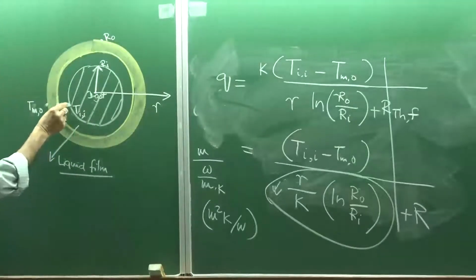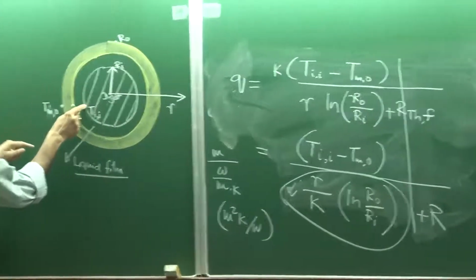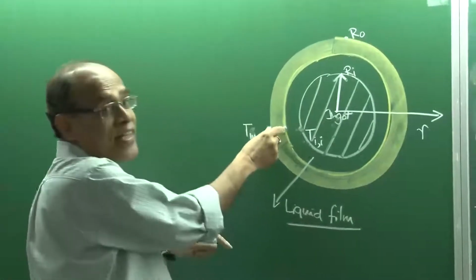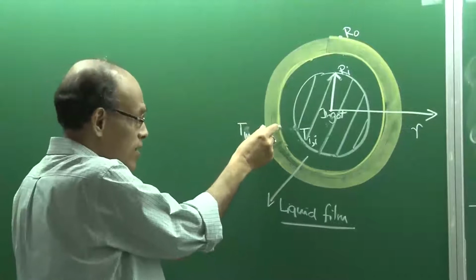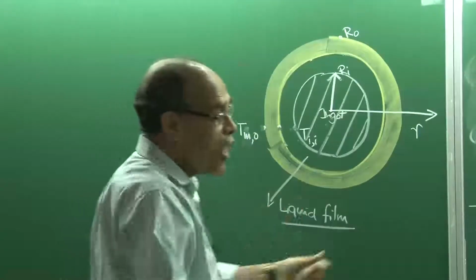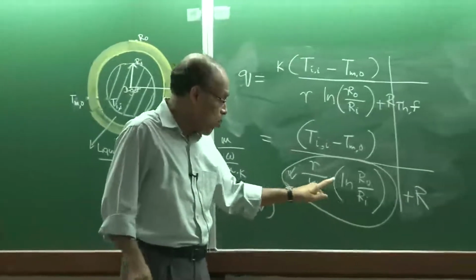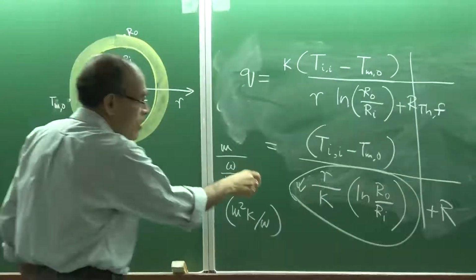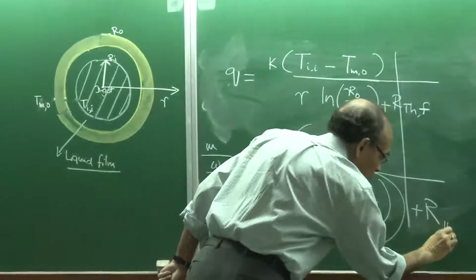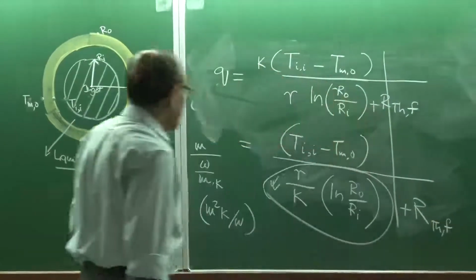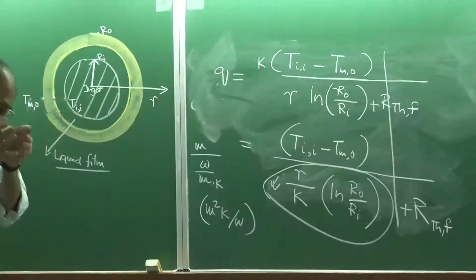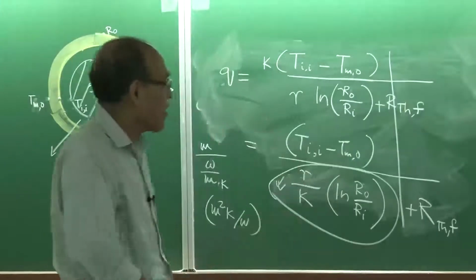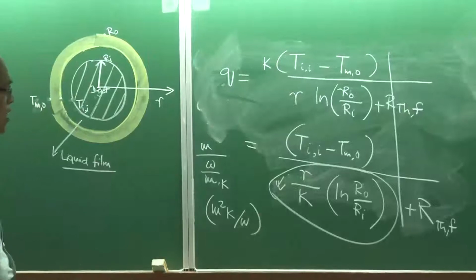When heat flows from inside, from here to here, it experiences resistance due to the thickness of the solid ingot, the solid resistance. And this is our thermal film resistance, which is created by the gap which exists between the solidifying ingot and the expanding mold itself.